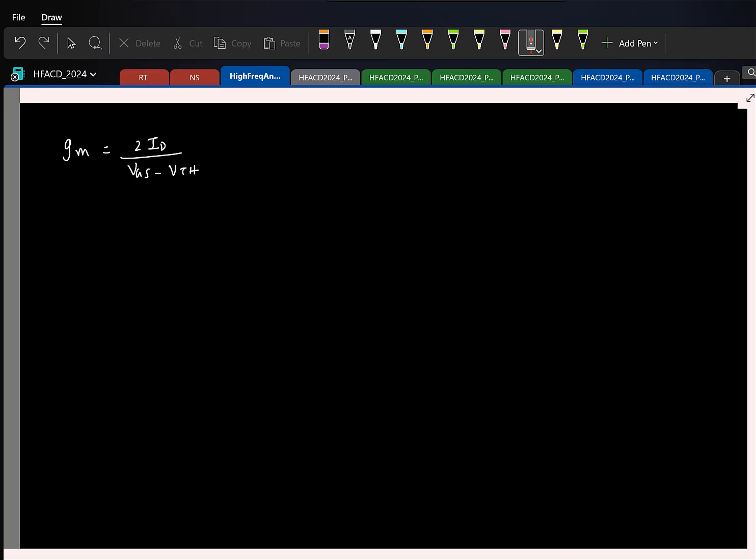Now think about it. I have some parameter that's going to change. I want to make this constant irrespective of any other changes in the system. What is the basic principle do you think I'll use here? Use some kind of negative feedback. That's all, right? For negative feedback, you take GM and compare it with the reference GM. For keeping a voltage constant, you take a voltage and compare it with the reference voltage.